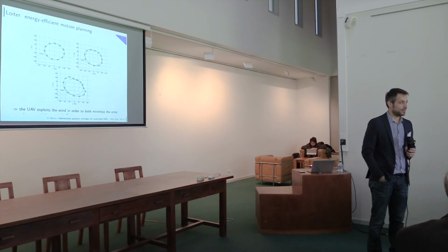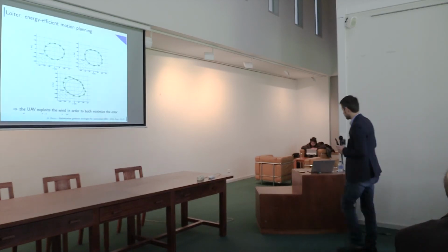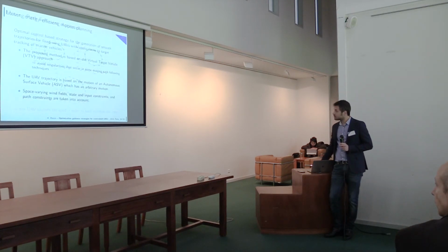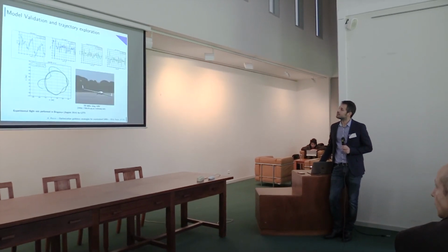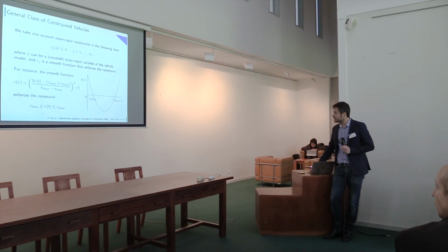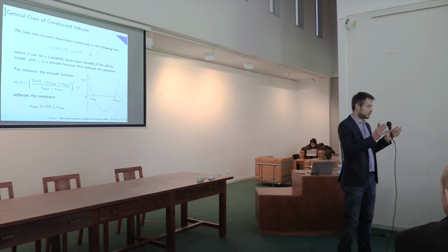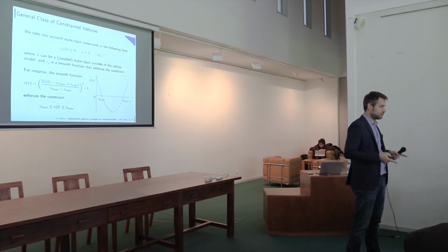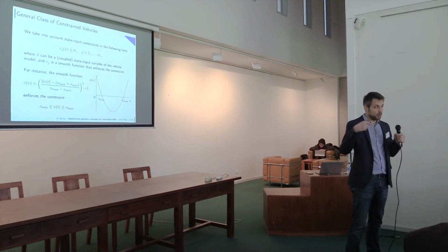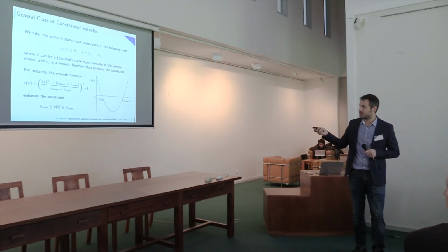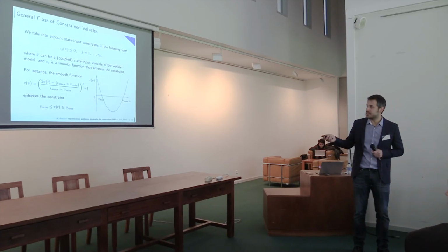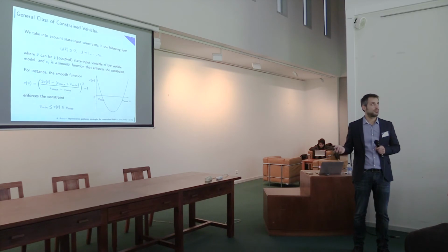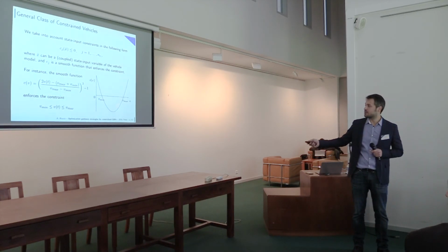Last question, there's this constraint on velocity and a graph. Do you understand what kind of... Yeah, because it's not my contribution here. So here, for example, for the airspeed, you want constraints: the airspeed has to be greater than the stall speed, the minimum airspeed, and less than the maximum one, probably. In that case, you have some non-smooth function describing these constraints. In order to include this non-smooth function in our optimization framework, we can use this quadratic approximation. So here we are saying that C, the airspeed constraint, has to be less than or equal to zero, negative in this case. So we have to be in this region.